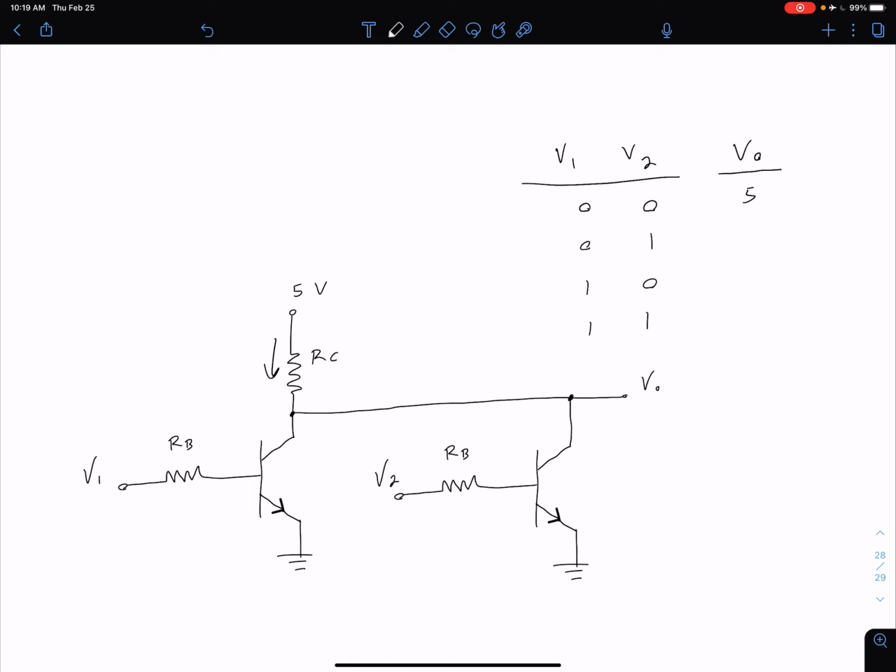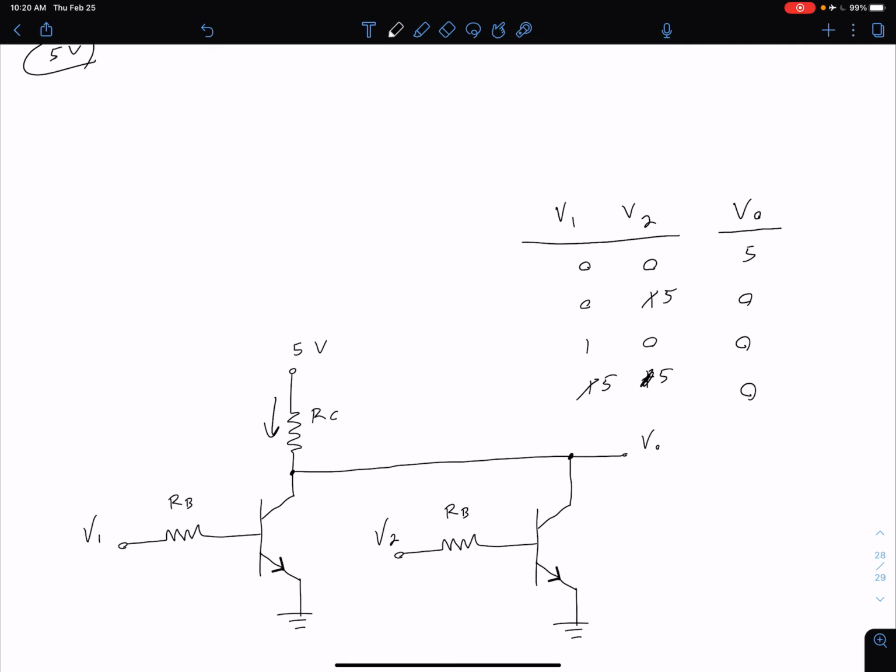And again, we're glossing over some details, but let's say it's small enough we can count it as a logic 0, so we get something that looks like that. And again, I realize now that I've used logic 1s here, but we could represent that as logic 1, or we could say instead of 1, these are 5 volts. So you'll see either representation. And so observing that, we can recognize that this circuit is providing a NOR function, so a not or.